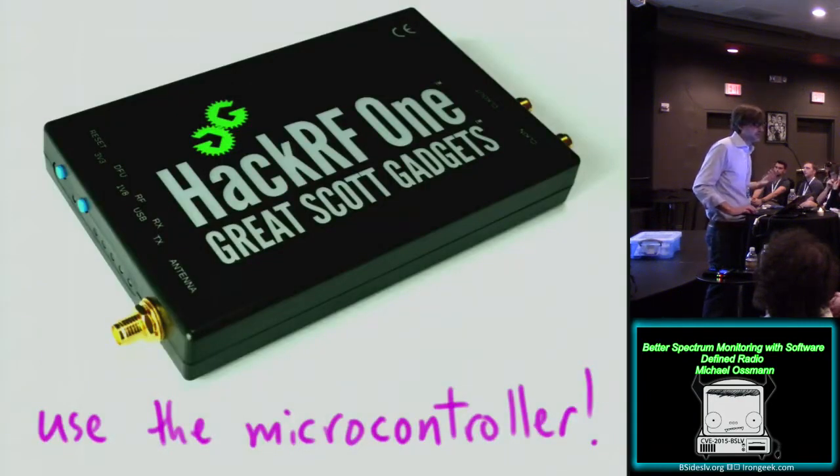So I'm using the microcontroller in the HackRF, and there are other software-defined radio platforms where we should be able to do this too. Any SDR platform where you have control of the tuning from the embedded device itself, as opposed to a control interface like USB. Generally speaking, I think HackRF is the lowest cost transceiver that gives us that capability. Unfortunately, I don't think the Realtek dongles have a way to give us that capability, although it would be cool if somebody figured out a way to hack that in.